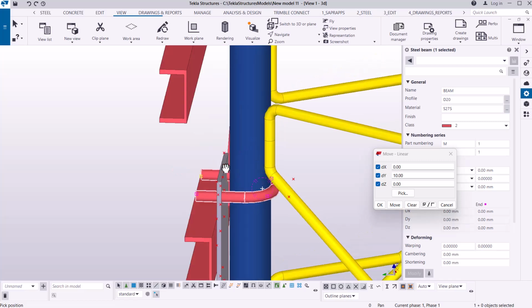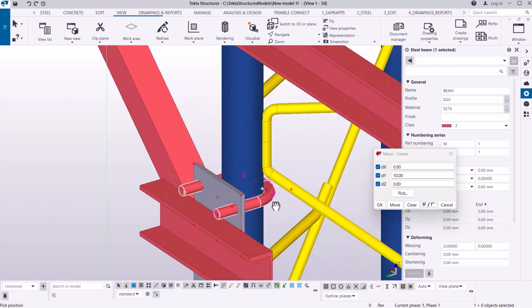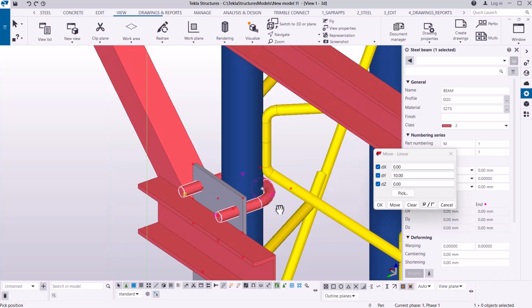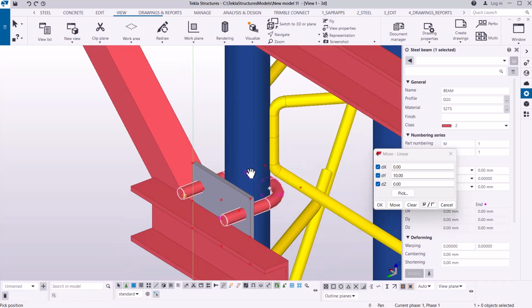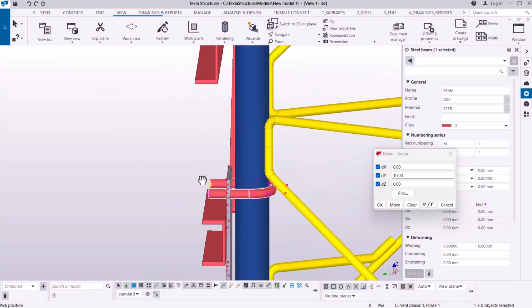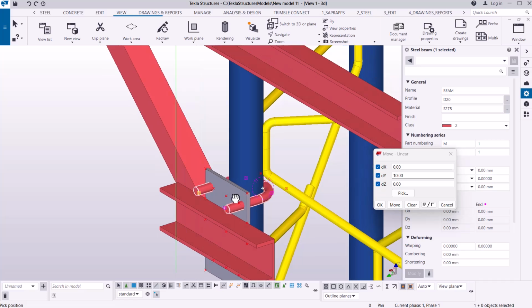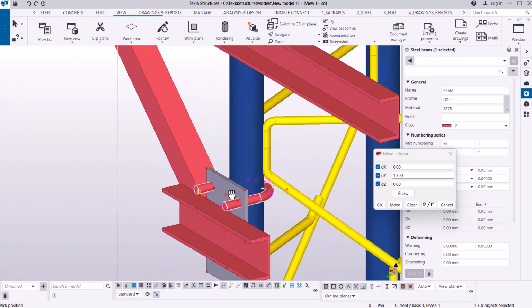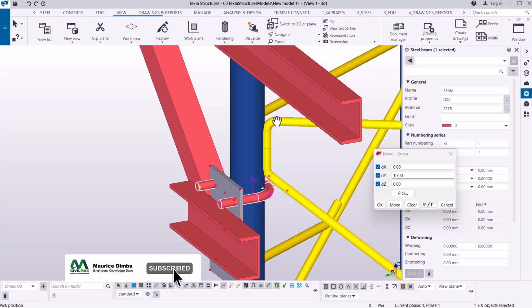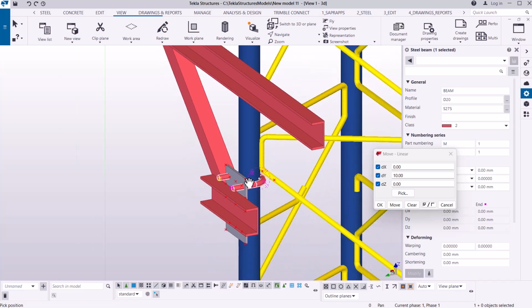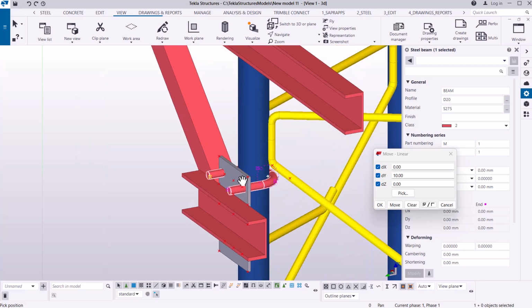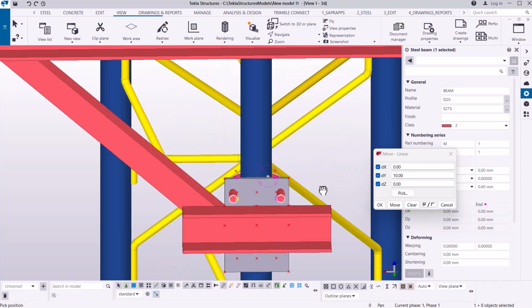And remember, we still have a gap here, and that gap will be filled by a deformed rebar that will add some more grip on this. So that we will add later on. That's why we've left that small gap there, because if you leave the plate directly on this leg, it might slide, and it might come down, and the rest will depend on these struts or bracings that will be subjected to some strain that at some time they might break. So we add some deformed rebars in between the leg and the plate here. So we have these in place.